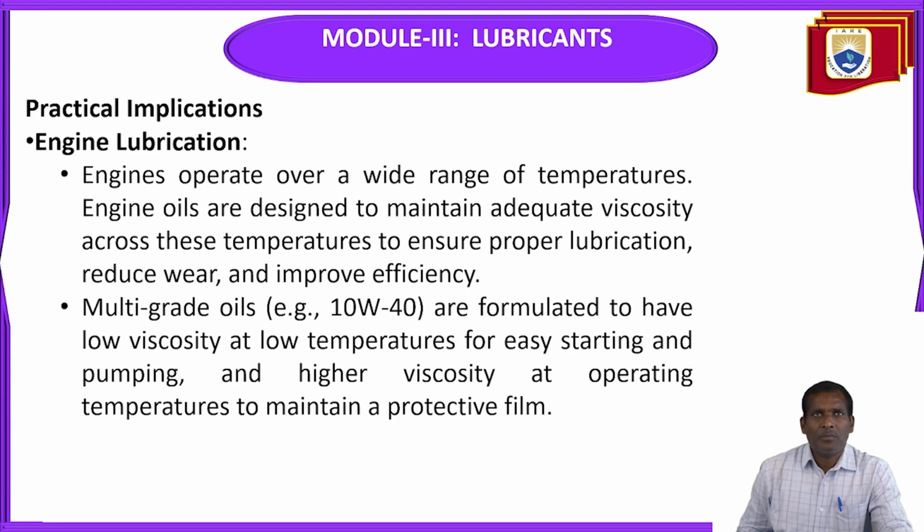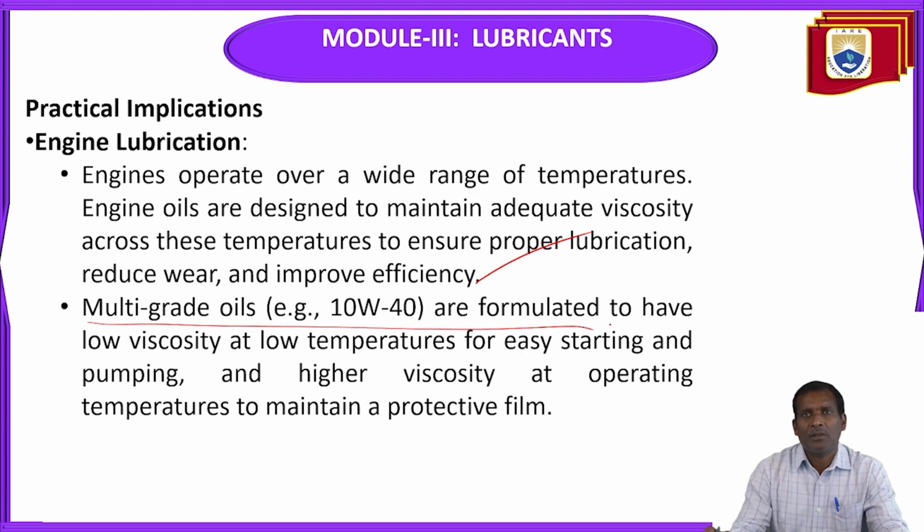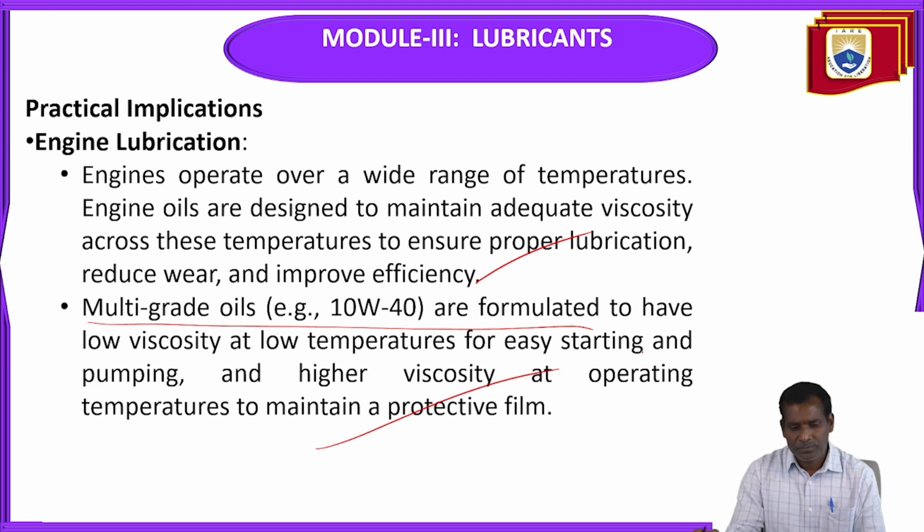So the practical implications are, first, engine lubrication. Engines operate over a wide range of temperatures. Engine oils are designed to maintain adequate viscosity across these temperatures to ensure proper lubrication, reduce wear, and improve efficiency. Similarly, the multi-grade oils, those are 10W-40, are formulated to have low viscosity at low temperatures for easy starting and pumping, and higher viscosity at operating temperatures to maintain a protective film.